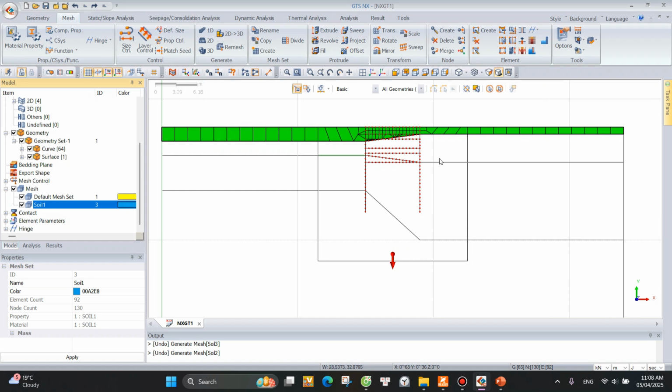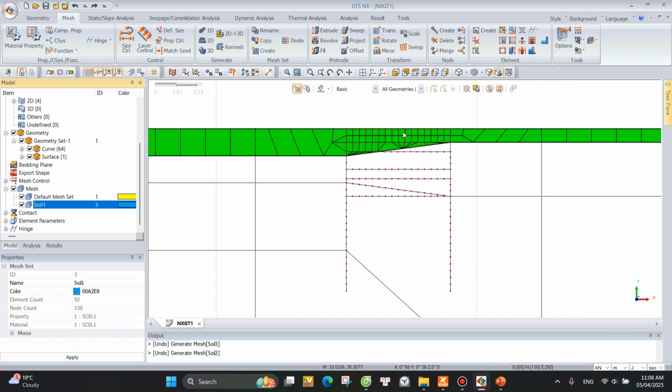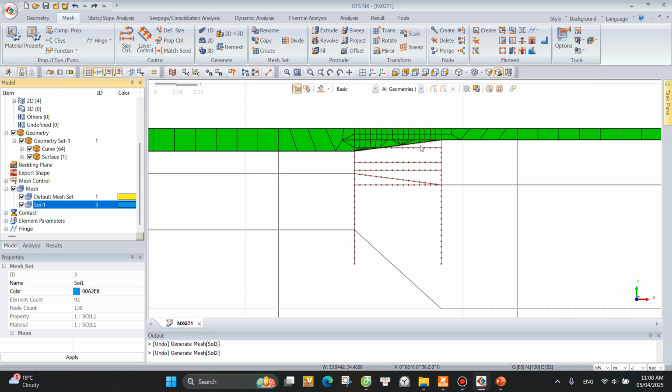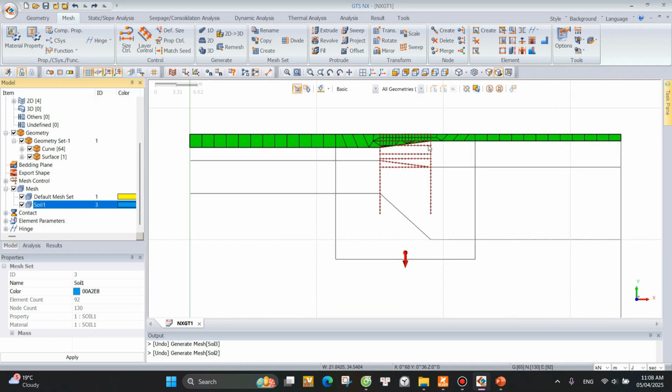this is full because you created the soil one. But when creating a mesh, we should, because now we want to have the excavation in here, so we don't want, actually we want to separate this area, and then later we can group this part and do it for the excavation. So that is the wrong way, because we did not separate it for the next stage. If you do it like this, you cannot do a full excavation like this.